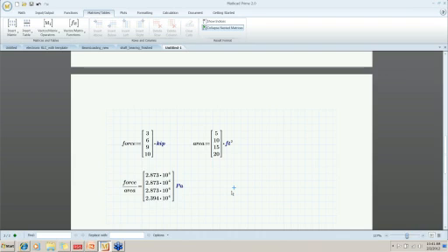We could always do this in Mathcad before, but you'll notice the units are a different font, which is nice. We already covered that. If we wanted to change this unit to a different unit, if we don't want that in Pascals, we could change it to KSI, and so now it's in units of KSI. We could change this to inches squared if we want.